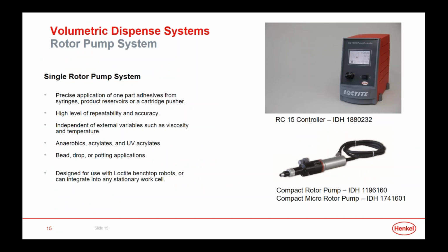The next volumetric solution we have is what we call our rotor pump system. Similarly to the previous valve, this is positive displacement, or volumetric. It's actually a pump that we dispense from, and it's got an auger inside of it. With each rotation of the auger, a specific amount of adhesive is dispensed onto a part. So again, this is a volumetric solution independent of external influences such as pressure changes, time changes, and viscosity changes.